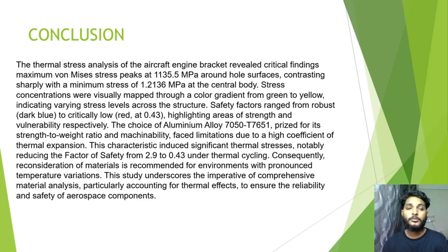Stress concentration is visually mapped through a color gradient from green to yellow, indicating various stress levels across the structure. The safety factor ranges from robust dark blue to a critical low of 0.43, highlighting the areas of structural vulnerability.